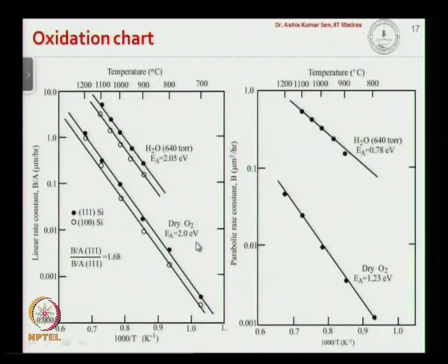Depending on the crystal silicon, here in this case we are talking about a 100 wafer, depending on the temperature and what type of oxidation you are talking about, either wet oxidation or dry oxidation, you would have the value for B over A, and the unit is micron per hour, and you have a value for B, which is micron square over hour. So you can find what is the value of A.